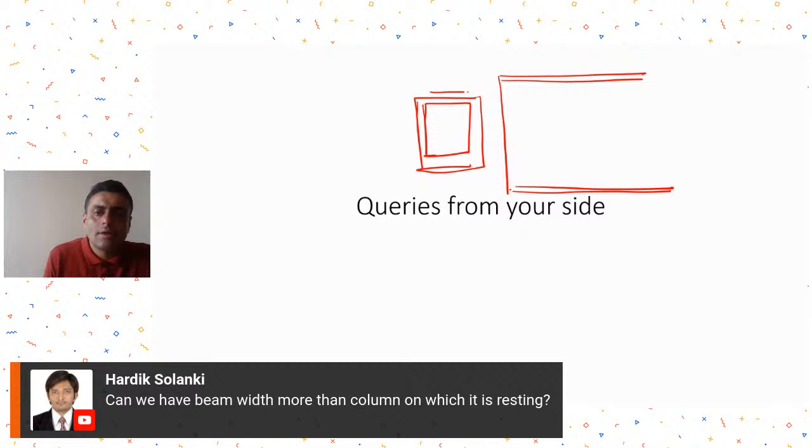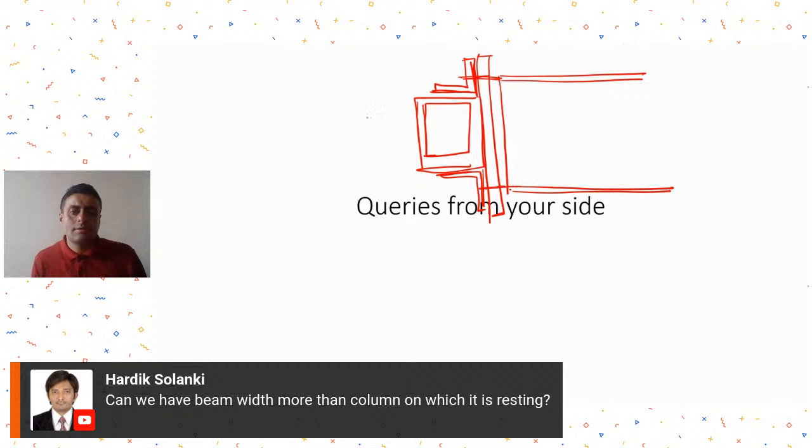So actually you can introduce a connecting element at the back like this, and then you can introduce some plate element like this, and here you can develop some connection assembly. Okay, this is the plan view. So yes, you can develop it. I showed it with a hollow section. The same thing can be done with other connection types also. So it becomes slightly complicated, but can be done.